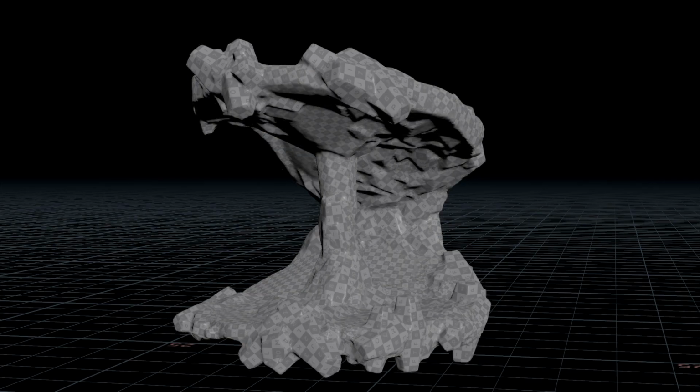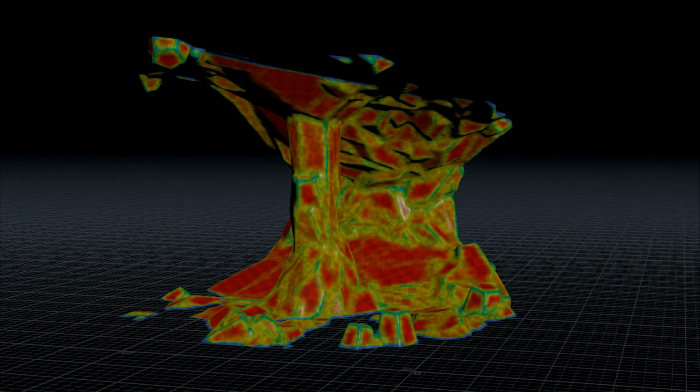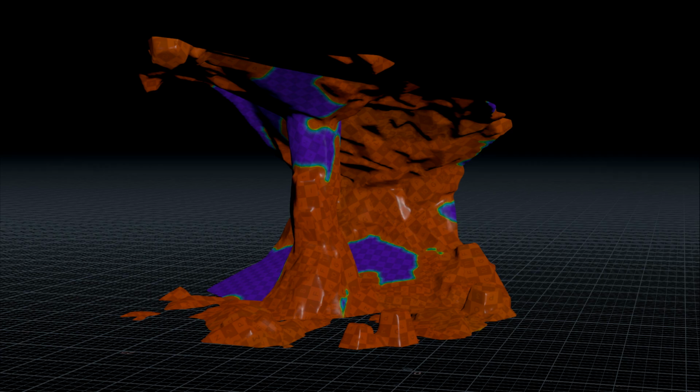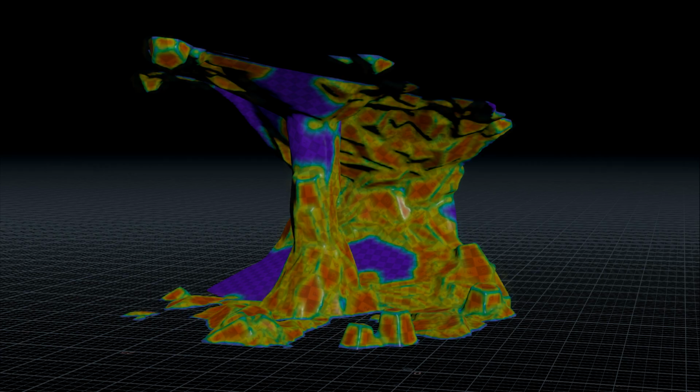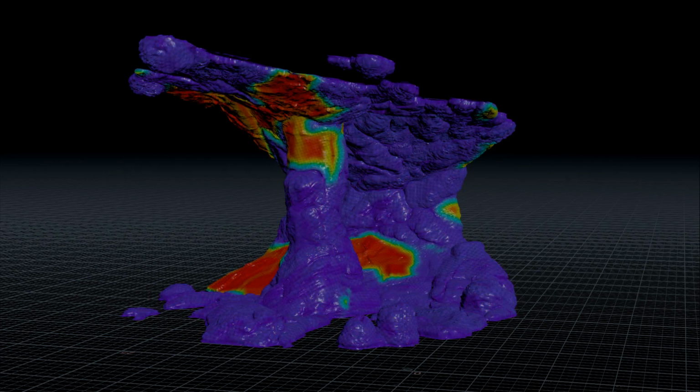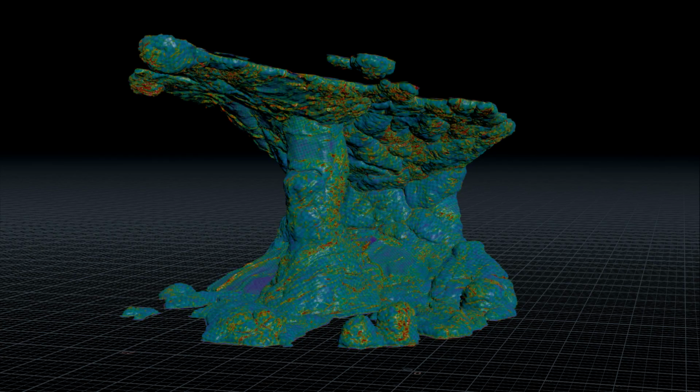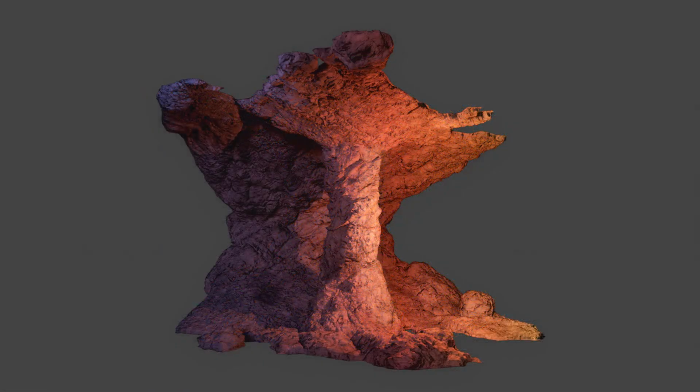This is merged together with the UV'd base shape. Displacement is applied on relatively flat areas of the mesh in two passes. One on the platonic shapes from copy to points, and one on the remaining geometry. This allows the user to specify two different displacement textures. At the end, I export some additional data in vertex color, which can then be used in Engine for the material.